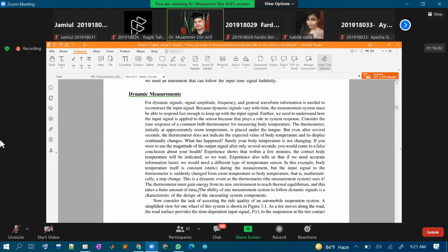You think of, I took some water with a thermometer, I want to measure its temperature. The thermometer is usually cooler than the water and it has heat absorption ability. So it will absorb some of the heat, reduce the temperature of the system. So although it looks like the water temperature measurement is very simple, it's not. It's actually dynamic. If apparently it seems, yes, this is another reason.